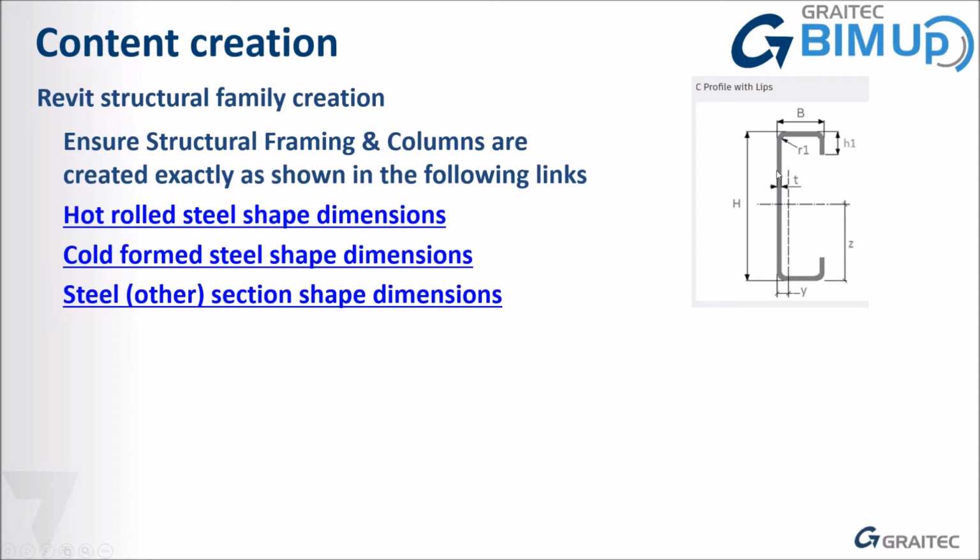What we've also found is that with this C profile with lips, the toes are on the right-hand side. If you put the toes on the left-hand side, so you have it created the other way, it can cause problems when transferring backwards and forwards.